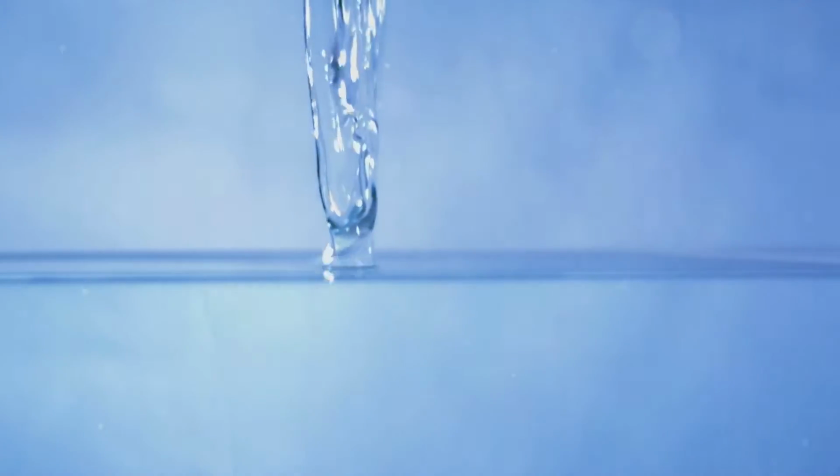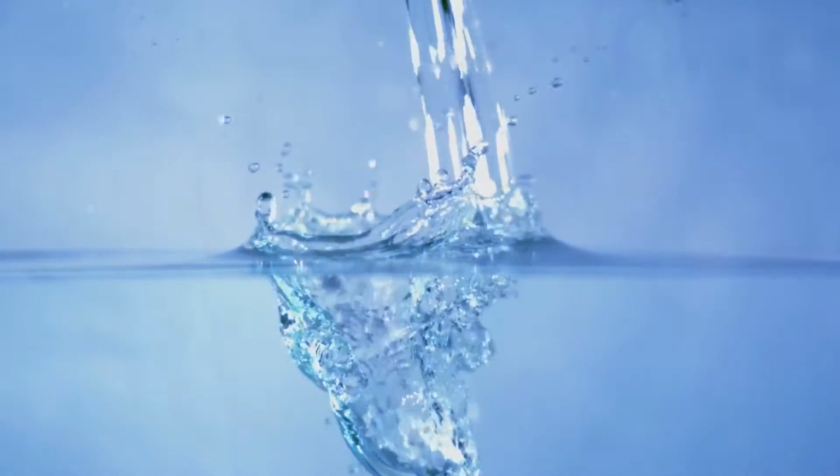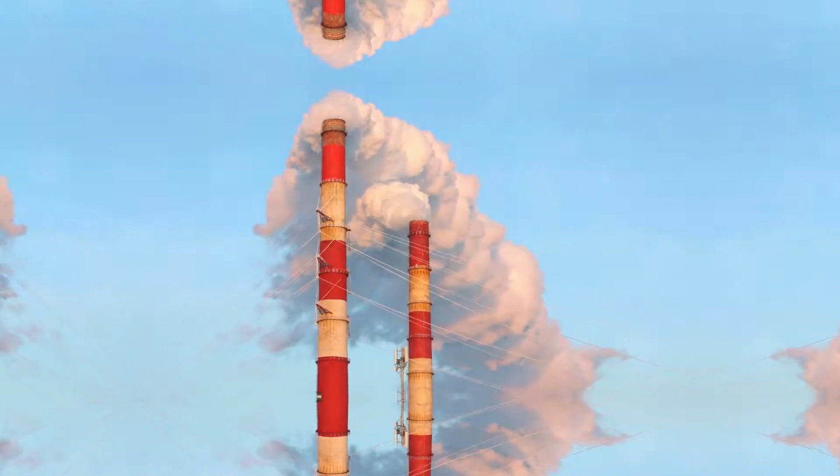The choice of breakup model, like TAB or wave, is crucial as it determines how droplets fragment under different conditions. Similarly, including evaporation models affects the temperature and phase change behaviors of the droplets, essential for applications like paint sprays or fuel injectors.